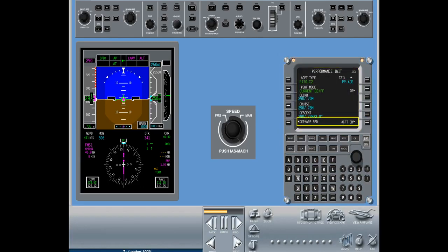The departure, climb, cruise, descent, approach, and go-around speeds are set in the Performance Initialization page 1 of 3. If a new schedule is desired, the settings can be modified in flight. The speed command is displayed in the Active Flight Plan page in CAS and Mach. VNAV will select the value resulting in the lower speed, which is shown in bigger characters.